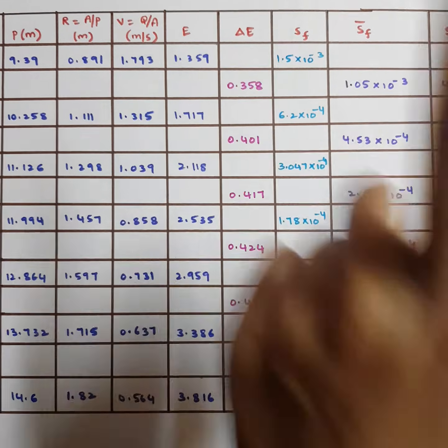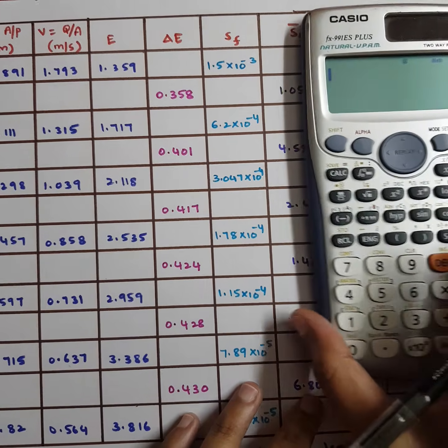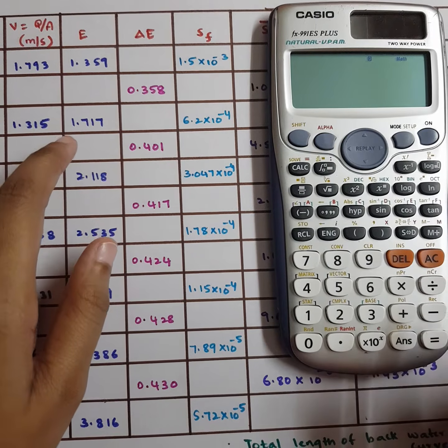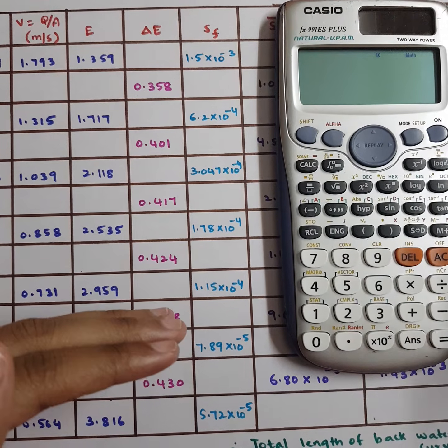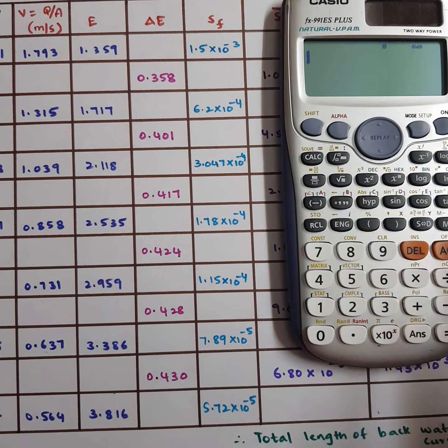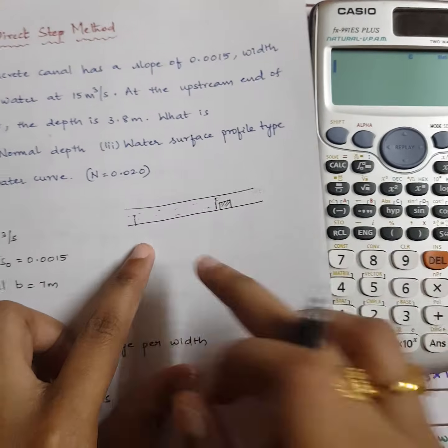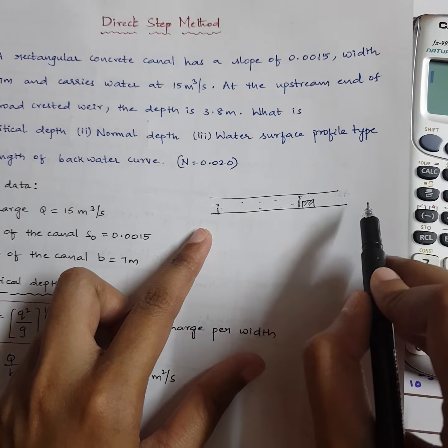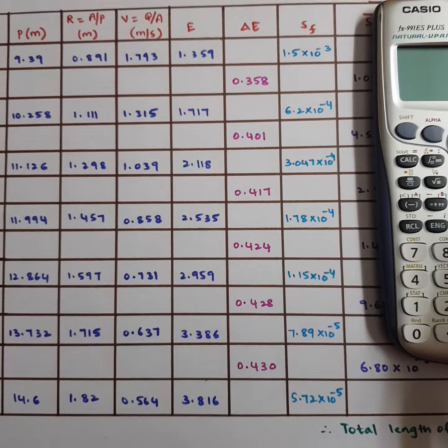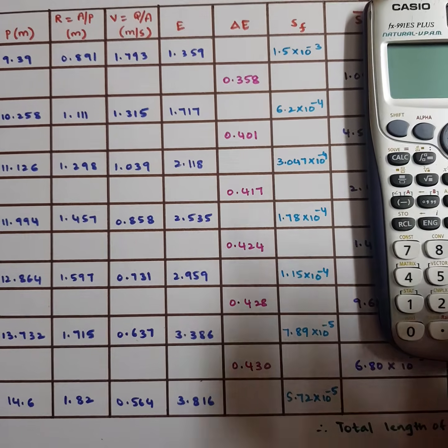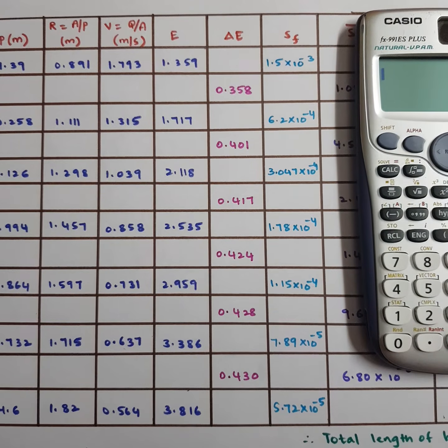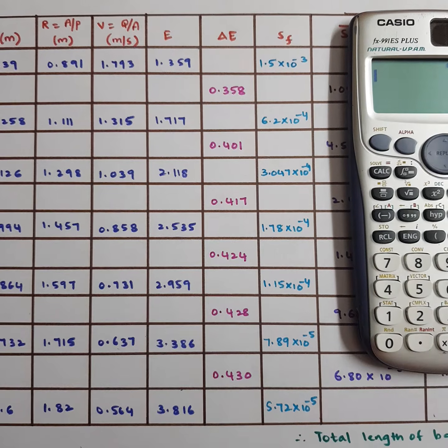Now let's start solving for delta E. What was delta E? I told you delta E is nothing but the difference of energy between the two intervals. So see here, the formula is E2 minus E1. Why are we writing E2 minus E1? As I told you in the beginning of the problem, we were traveling upstream, right? So hence we will do E2 minus E1. Okay, when you're traveling downstream it will be E1 minus E2. And you may start off with any assumption. I am saying I'm traveling upstream, hence I'm doing E2, since when I'm moving forward the forward value will be bigger, hence I'm doing E2 minus E1.